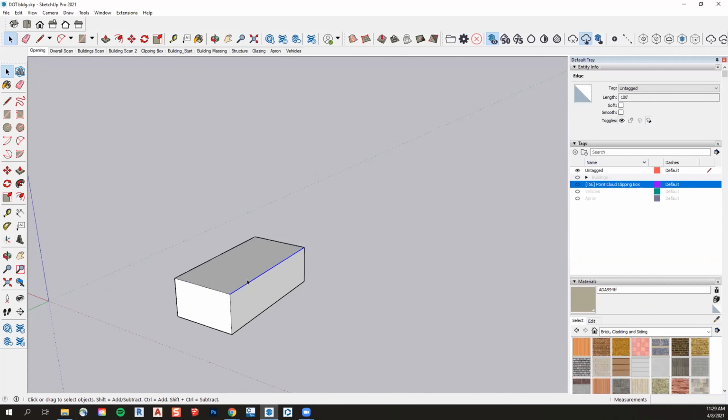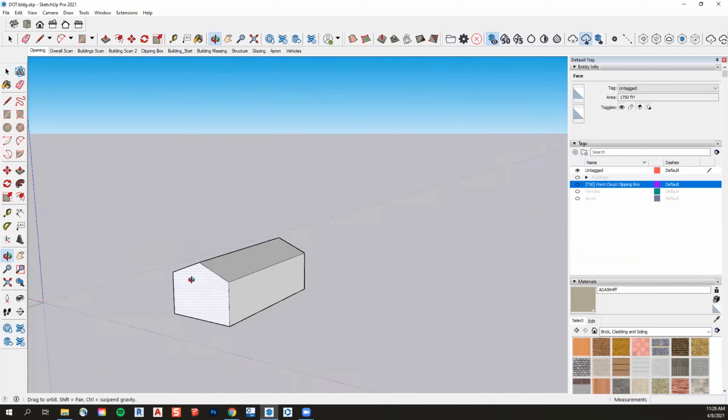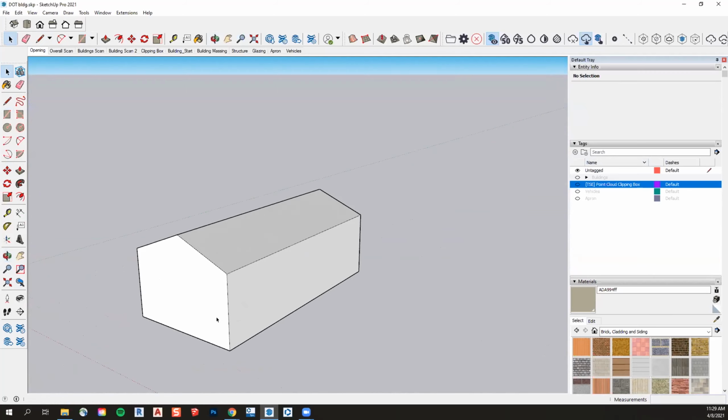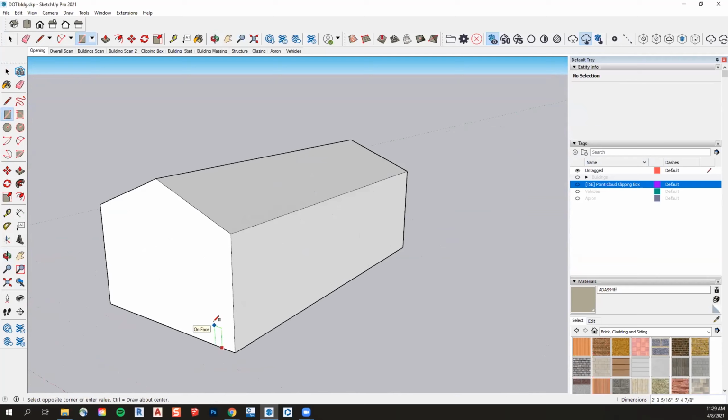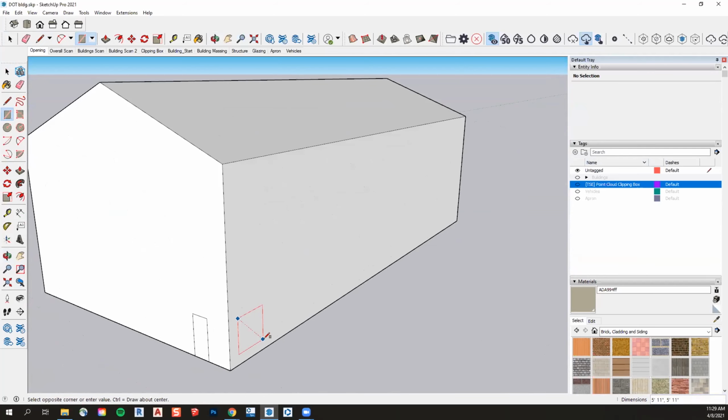We've got our facade here, that's 100 feet. And maybe we want to start to alter this geometry to give it a better building form. So in this case, if we've got a gable roof and we want to move it up 10 feet, give it a little bit of pitch, we can use these same tools to create a little more detail if necessary. So for example, if we've got a door here, 3 foot by 7 foot door, and maybe a collection of windows on this facade, we can copy them pretty quickly